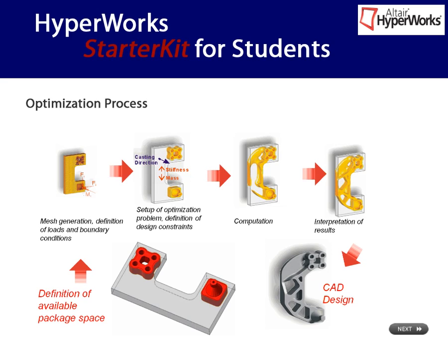at all. What follows is the typical FEM analysis process including meshing, material definition, placing constraints, forces, and so on. Check the analysis results for any errors and warnings, as these issues will become part of the following optimization run. Also, the results serve as a baseline for the optimization.